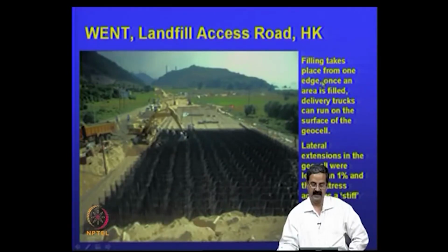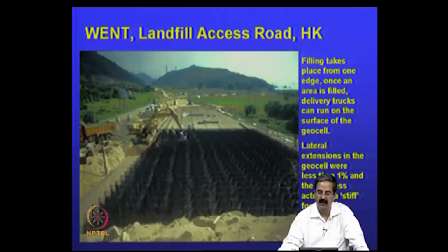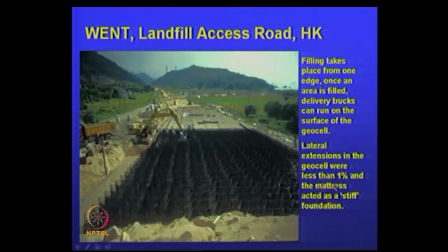So, filling is being done. Filling takes place from one edge. Once the area is filled, delivery trucks can run on the surface of the geocell. Once it is completed, one can go ahead and work on it. Lateral extensions in the geocell were less than 1%, and the mattress acted as a stiff foundation. It is a very good system here.